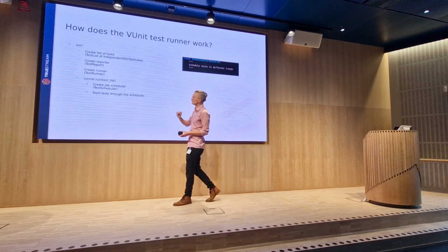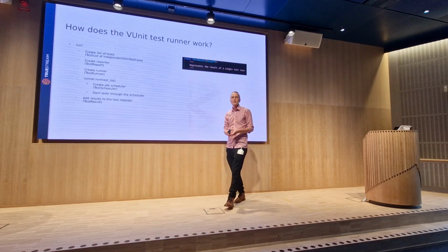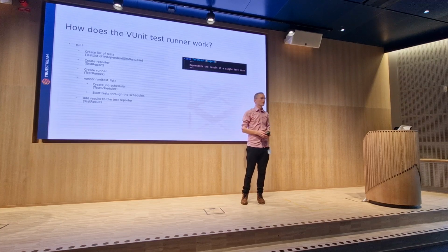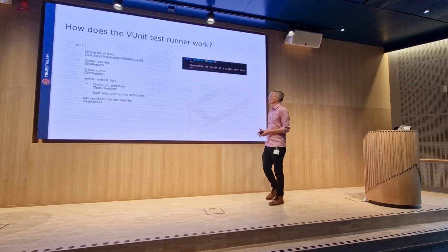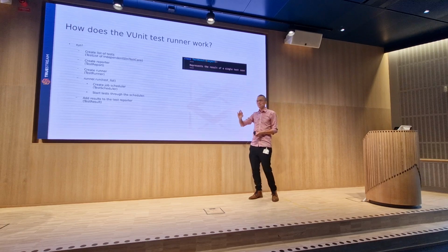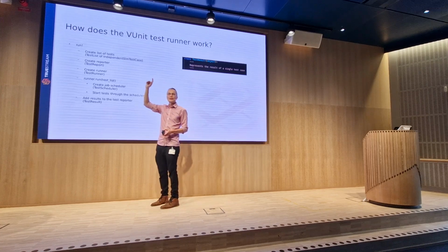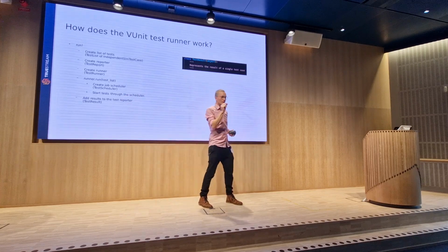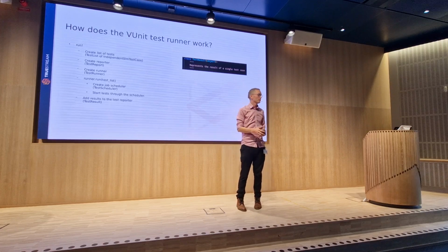And with the scheduler, we can start the tests. As the tests complete, you need some object to handle the result of the test, so you can print at the bottom. And there's a test result object for that. So, this is how VUnit works in this regard. On the next slide, we will see how we overload some of these objects in TS-FPGA. We inherit from them and then we just adapt what we needed in our use case.